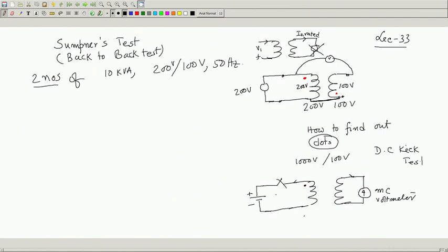Now, you close the switch. The moment you close the switch, it is not an AC supply, but there will be a sudden change in flux. Therefore, we expect there will be an instantaneous induced voltage. And if this happens to be dot, see, moving coil meters have plus minus marking, is it not? If current enters, it gives positive.